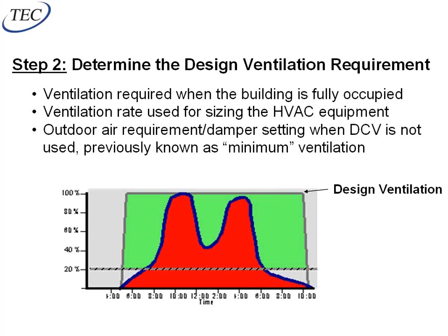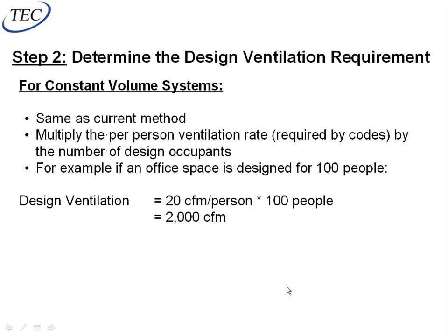So like I said, for a typical office building, the design is now 5 CFM per person plus 0.06 CFM per square foot. So my baseline in this case becomes the 0.06 CFM per square foot, which is the 20% on this line, and I get to modulate the people part, right? So from 0 to 20 is what's taking care of my building. From 20 to 100 is taking care of my people. I'm going to modulate those back when no one's there or when less people are there.